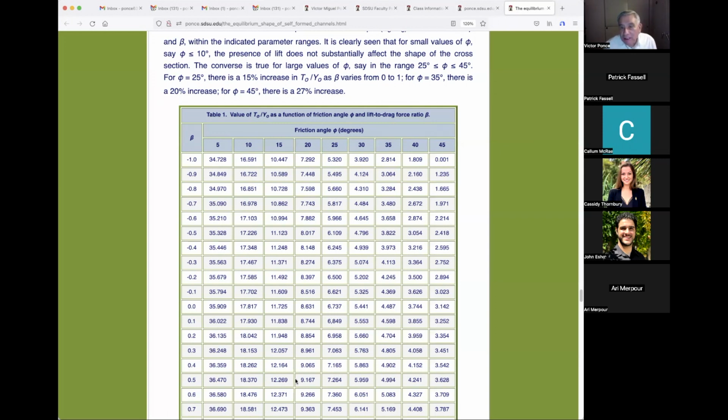So that subscribes to the rationale that Chow said. Actually, Chow didn't say it. Chow just said that for a channel to be considered hydraulically wide, the width to depth has to be more than 10. And he's correct. But the next question is, are channels likely to be less than 10? And the answer is not likely, unless you put it together. If it's a channel built by nature, self-formed, it'll go 10, 15.